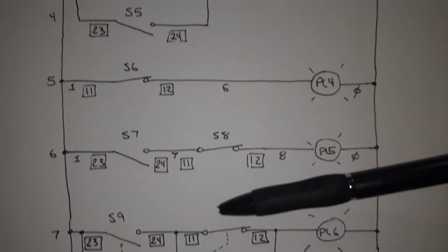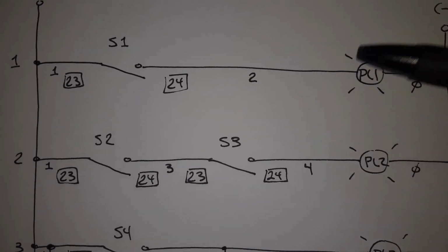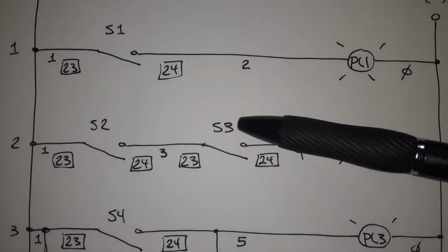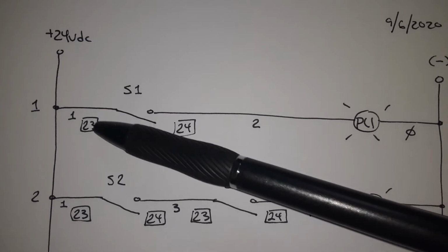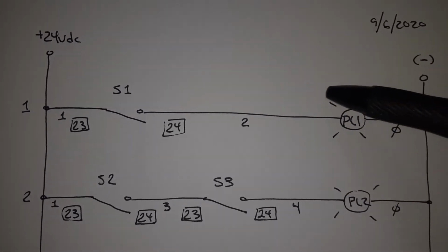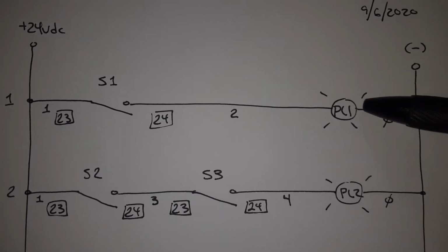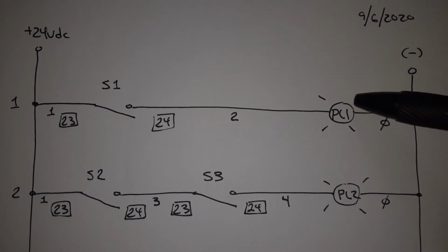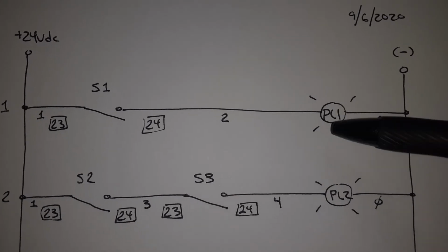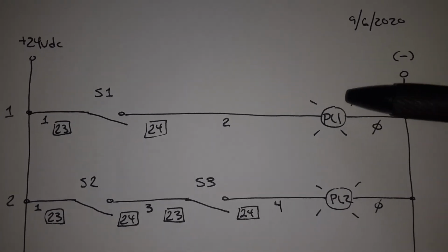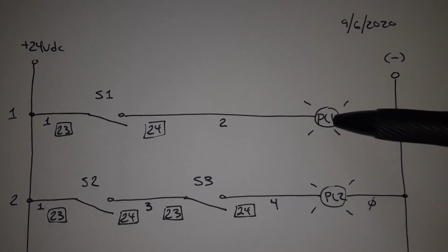So these switches, these are all selectors. You turn them on and they stay on until you turn them off. And that's fine if that's what I'm after, but imagine this situation. Let's say I turn on power on switch 1, and let's say this is actually a motor, like a mixing motor. And then the power fails, and the power comes back on, the mixer starts immediately. Now that might not be a bad thing, but imagine if the power turns on and off very quickly, 50 times, the mixer motor will probably burn out because it's not designed to switch on and off very quickly.